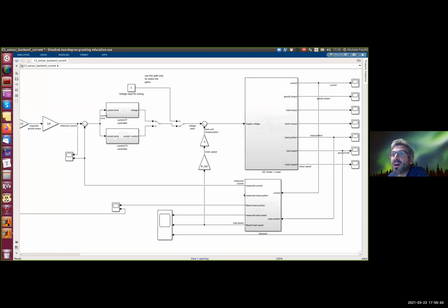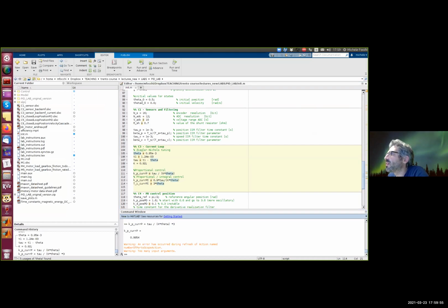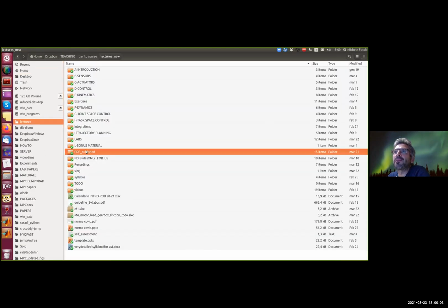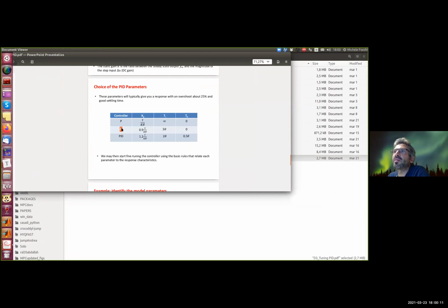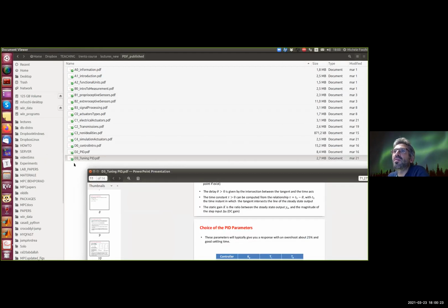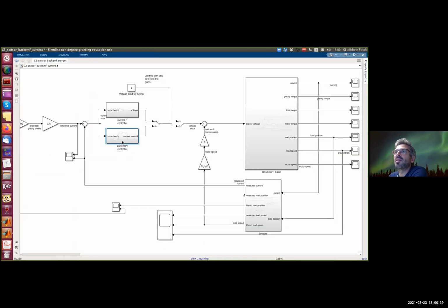So keeping the same response parameters for Ziegler-Nichols, we go to the table of the PI controller. Sorry, I think in the slides there is a typo. No, I corrected the typo. Yes, it was PD. That was wrong. So we go here and we get these two values. So we replace the TI variable with this theta and KP with this one. We evaluate this and we have to implement the PI controller.